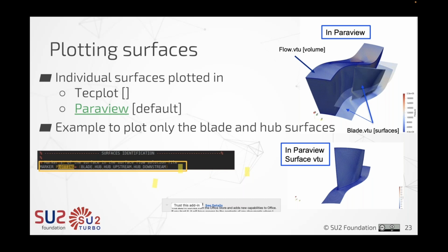Yeah. Just briefly, the advantage of using that total pressure and temperature condition: normally in industrial applications, it's not a fixed scalar value. Like in the wind tunnel when you're testing an engine, you're going to have a profile, a radial variation from the hub to the shroud.